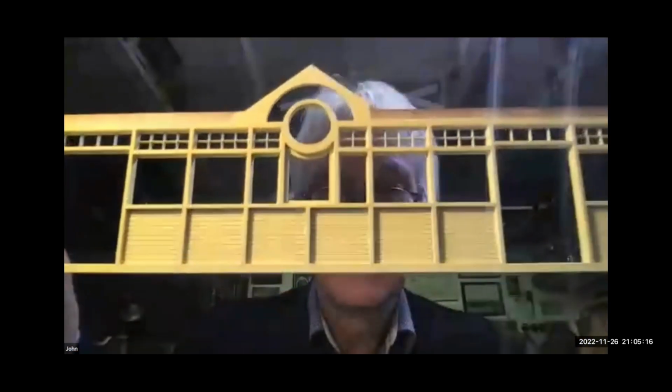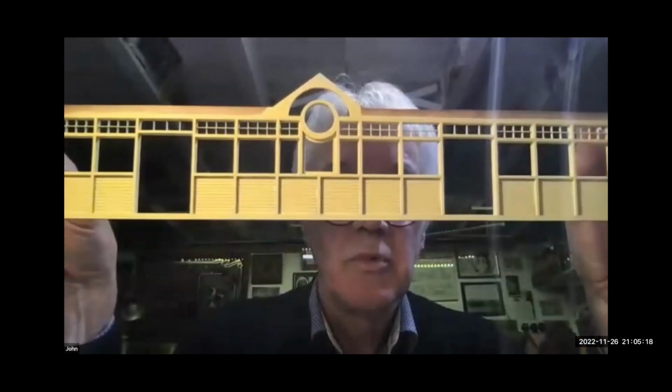I think it probably depends on your machine. Looking at this, that's the inside of it. It's very fine. Those window frames are probably only 0.5 mil wide. What I'm meaning is that whoever's machined it for you has taken your drawings, converted it into CAD, and then had to make an allowance for the thickness of the laser.